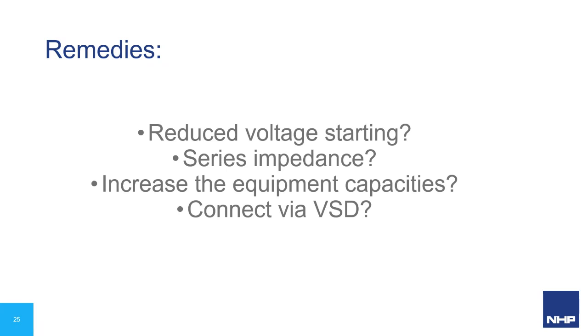So if we connect a VSD to a motor that runs constantly at full speed, it sort of defeats the purpose of using a motor that was designed to improve the previous models by 1% when we have an inefficiency of more than 2% out of the variable frequency drive. So these are all of the things that need to be considered. IE3, IE4 motors are not compulsory in Australia. MEPS 2, or IE2, is the performance level that's required by the MEPS system.